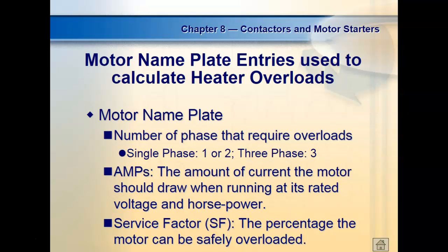It doesn't really bother us if we plug these motors in. Why is that? Because the only inertia it's got is the inertia of the rotor. So we're not running our motors under load. But don't reverse that. You might blow the fuses. So service factor, that's going to be on there somewhere. It's going to be labeled SF.